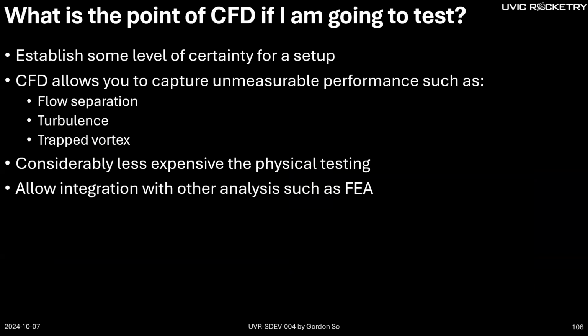So you may ask, what's the point of CFD if I'm going to test it anyway? Of course, you want some kind of certainty about a setup, because you usually won't start with your actual geometry, since sometimes you don't know if your setup is correct. Usually you can look back into previous test data to fine tune what you're seeing. And at the same time, CFD allows you to observe certain things that you cannot really measure or record. For example, flow separation is harder to observe.